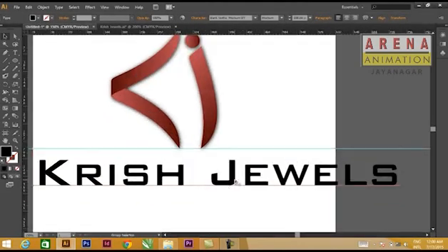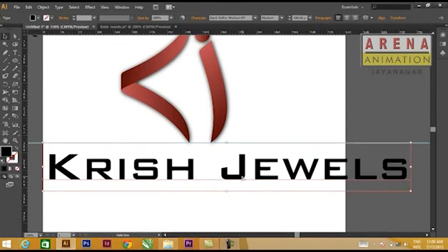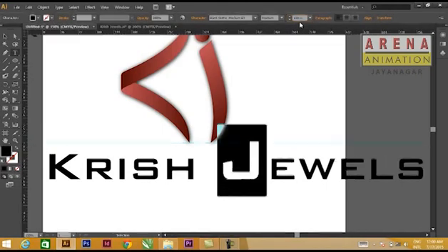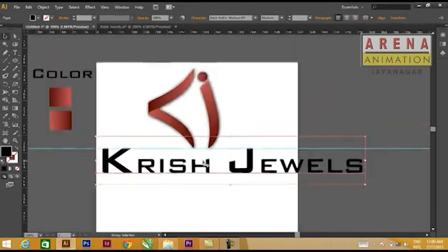I will use this font. The font is Bank Gothic Medium BT. Here I'll select J. I'll change the font size from 100 to 150 and even K, 100 to 150. Done.